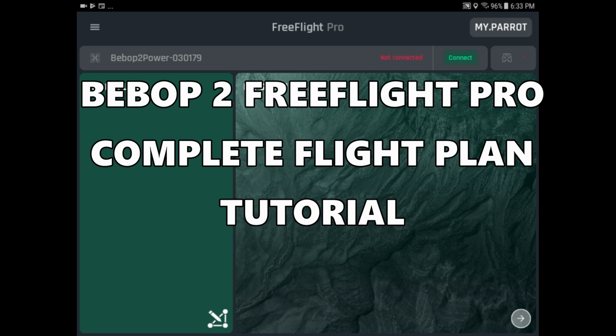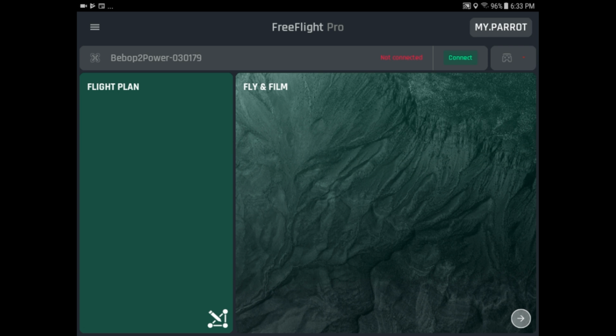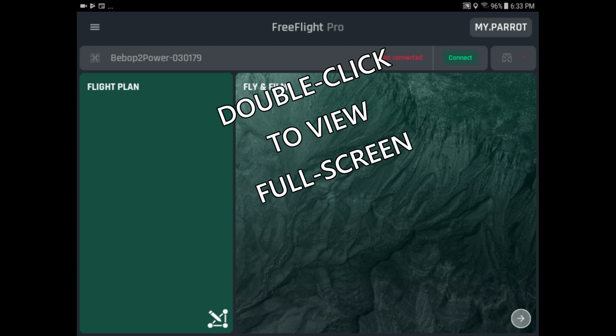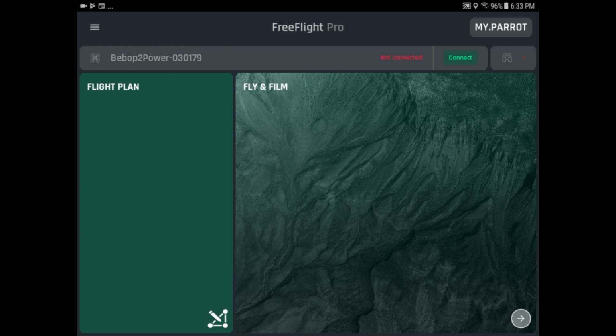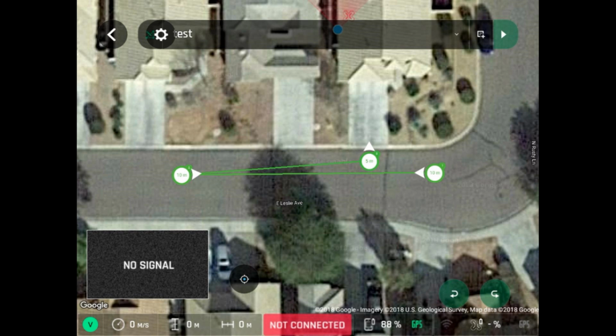If you haven't ever created a flight plan, there's about three different things you want to do before you ever create one that goes very far away. First of all, create a flight plan with two or three or maybe four waypoints that are real close by where you take off, so that if you've done something wrong, it's not somewhere far off in the distance where you can't find it. That's the first flight plan you ought to make.